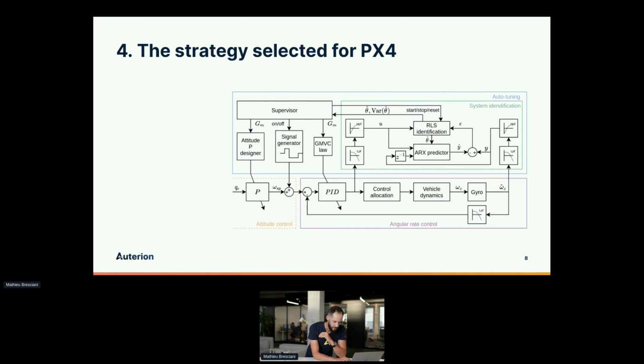For fixed wing, what you need to do is fly at trim airspeed, so then you get the correct tuning for trim airspeed. Then you have to define the max airspeed and the min airspeed, and we already have the scaling for the airspeed in there. For flaps, at the moment, it's not supported. The control will not adjust directly for flaps. The flaps will define the trim, but the control gains themselves won't change for trim settings.